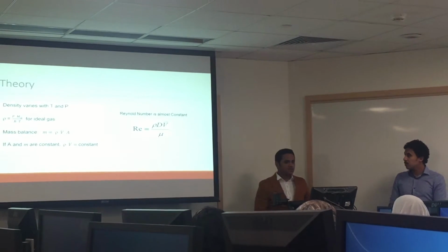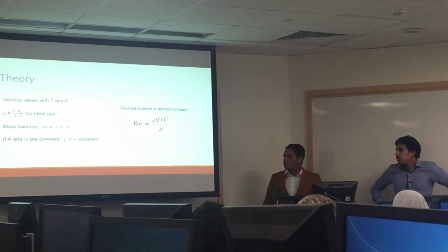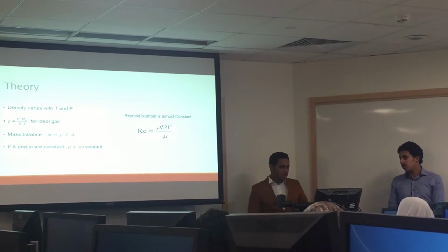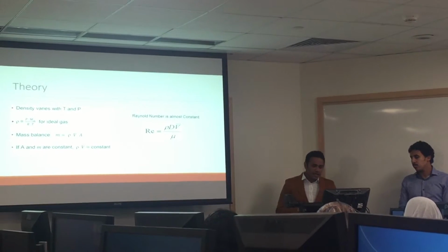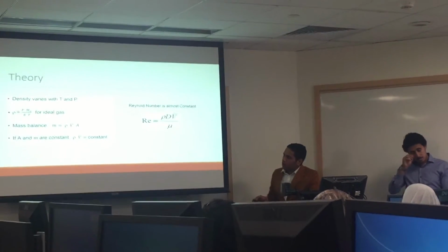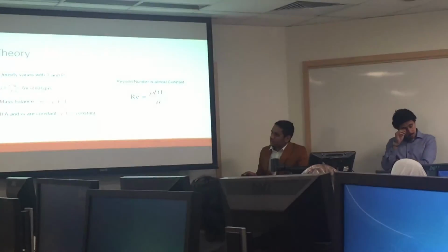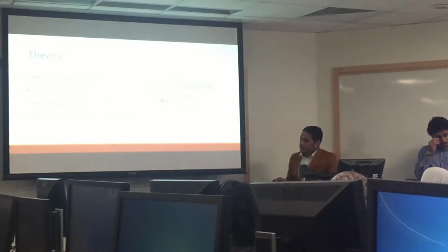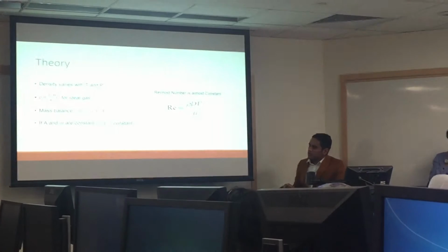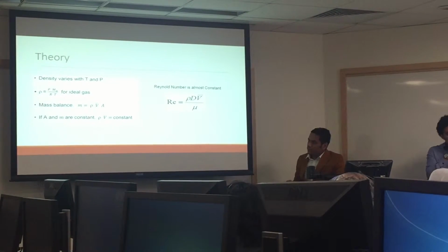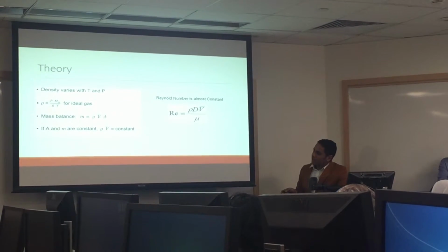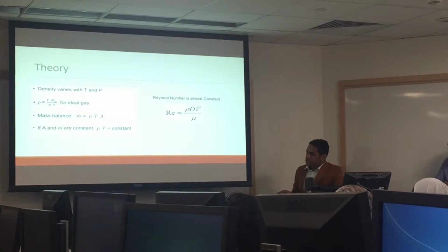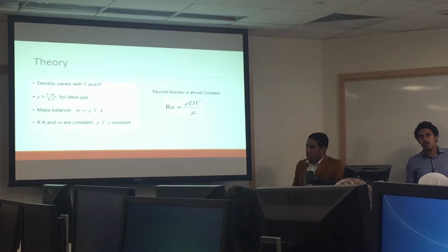Because we wanted to study how the pressure drop varies with operating pressure, here is our theory. According to the ideal gas law, holding all other variables constant and increasing the pressure, the density will increase. Also, because we were holding the mass flow rate constant and the area of the tube was constant, the product of the density and average velocity must have been constant.